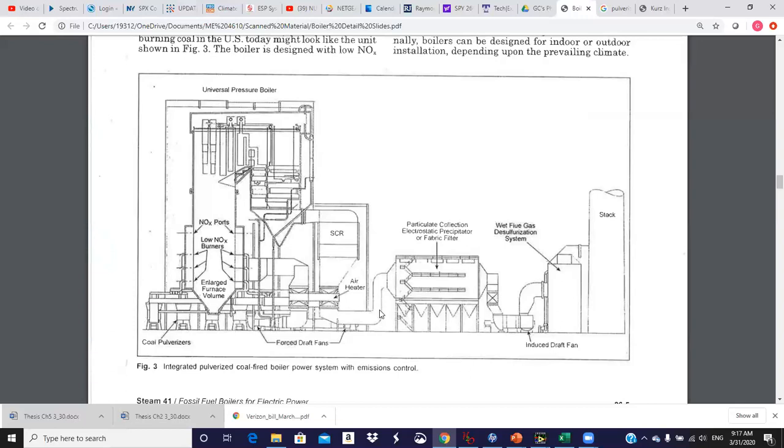A terrible situation. I don't know how that happened, well, I do know how it happened. When these units were put in, they didn't even have precipitators. They were just blowing the ash, and it was totally unacceptable. So when they retrofit, for some reason, they didn't want to move the fan on one series of units. And so the fans are dealing with the ash-laden flue gas, and it's a terrible maintenance issue.